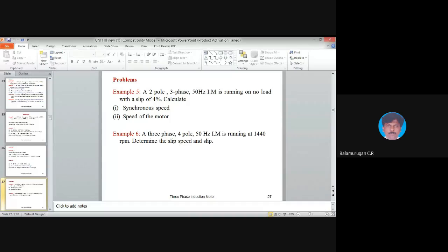And here you can now consider the three-phase phasor diagram. Okay, like this you can consider. So you know all these angles will be 120 degree. So now you are going to draw for theta equal to 30 degree. And here what is the phi x value? That is 0.5 phi m. And y value will be equal to minus phi m. And z value will be equal to 0.5 phi m.